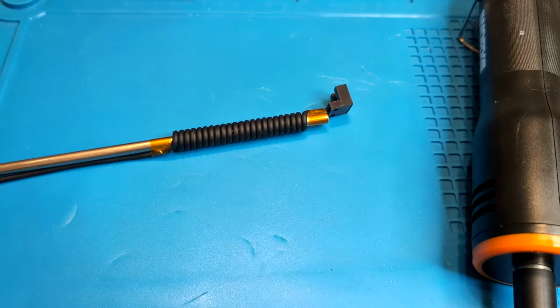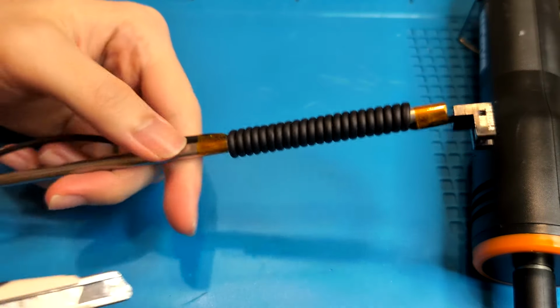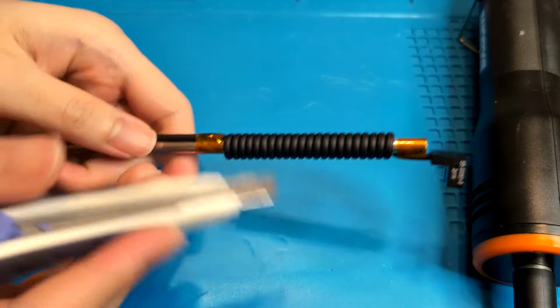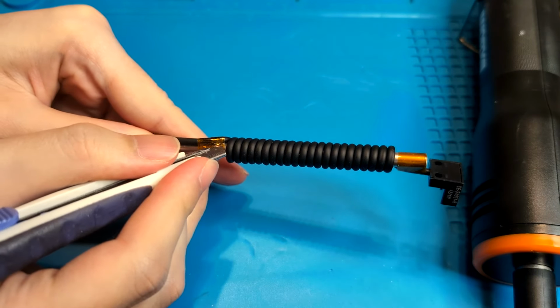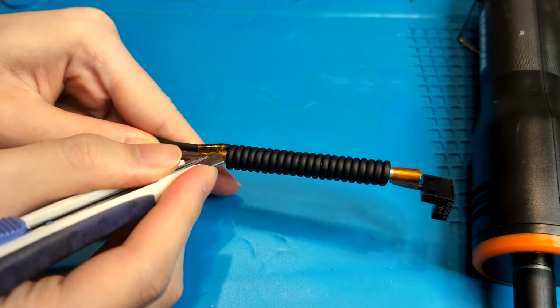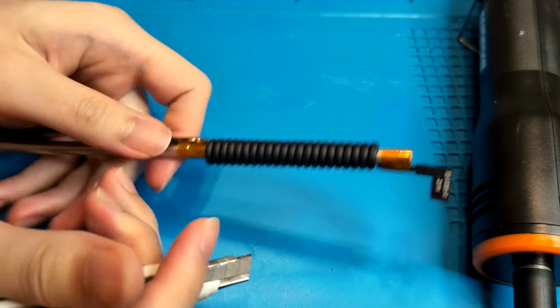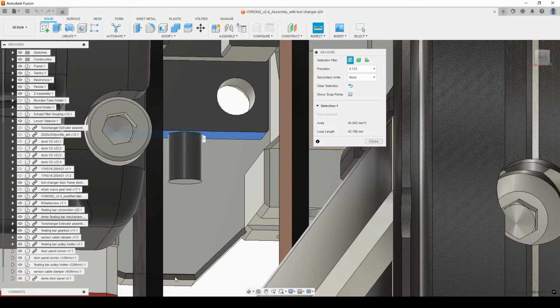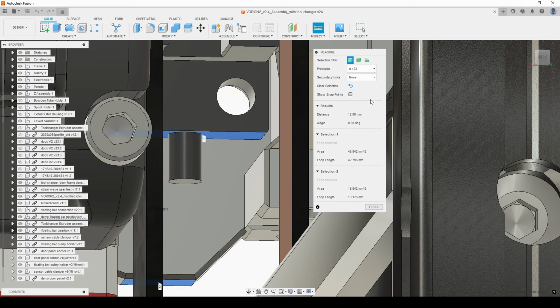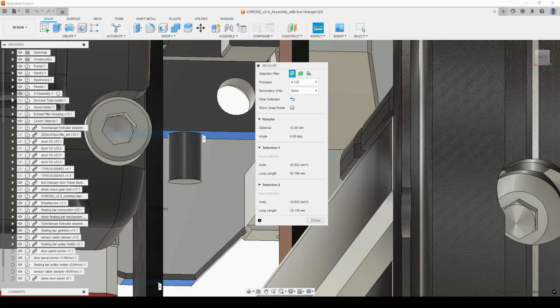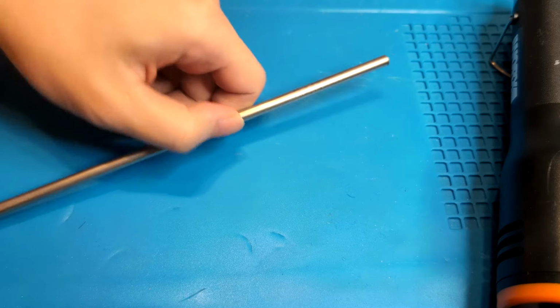Adding extra coils can prevent the coils from straightening. Therefore, I have decided to have 2 extra coils on the bar, bringing the total to 22. The sensor has a 12 mm clearance to the floating bar edge. To achieve this, I use a 6 mm stainless steel rod.